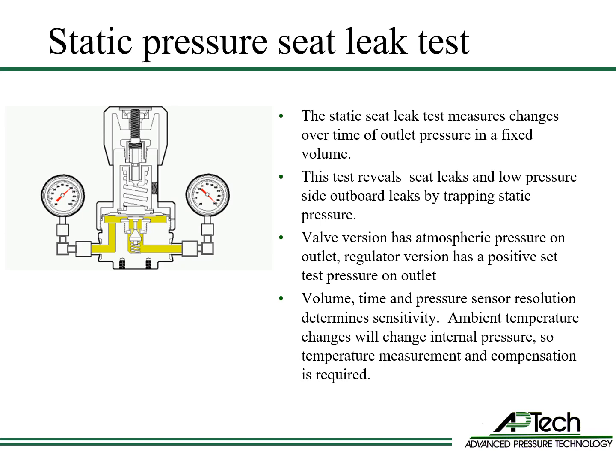Test sensitivity is determined by trap volume, pressure sensor resolution, test pressure, and time. Ambient temperature changes over time will also affect test accuracy, so temperature measurement and compensation is required. Many customers perform this test after helium leak testing and also before system startup.